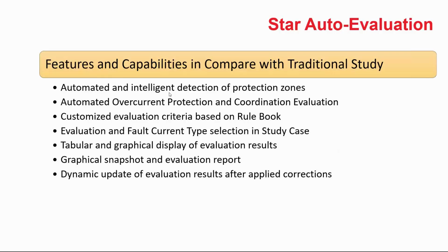It would automatically evaluate all of the protection and coordination zones. What I mean by all is all of the selected zones from the one line. So it's up to you to decide the whole one line or any portion of the network that you would like to do the protection and coordination studies.